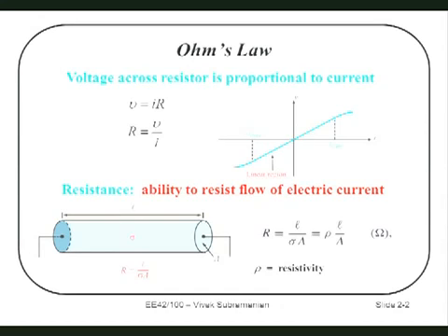Okay, the units of, so let's think about it. What are the units of sigma? 1 over ohm cm, right? What is 1 over ohm? Siemen or mho, right? So it is Siemens or mhos per centimeter. Break that up into its fundamental units, and you can figure out. Okay, so we have rho and we have sigma. So that's how we calculate the value of a resistor.